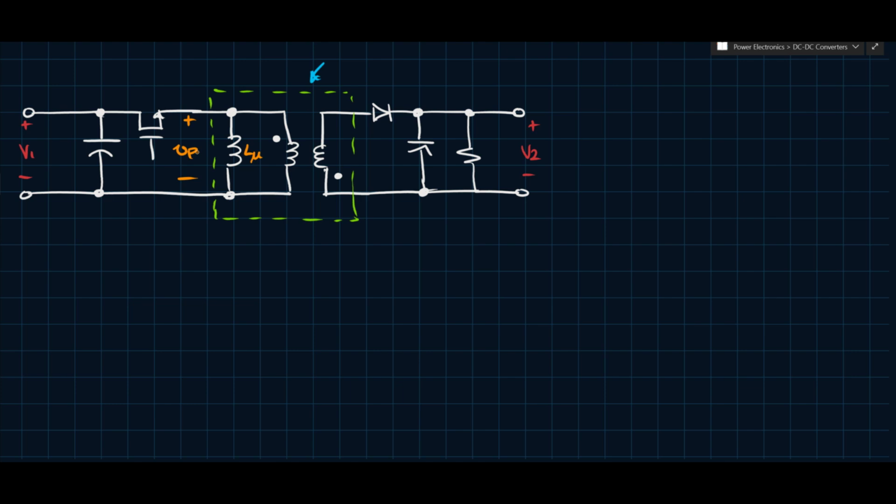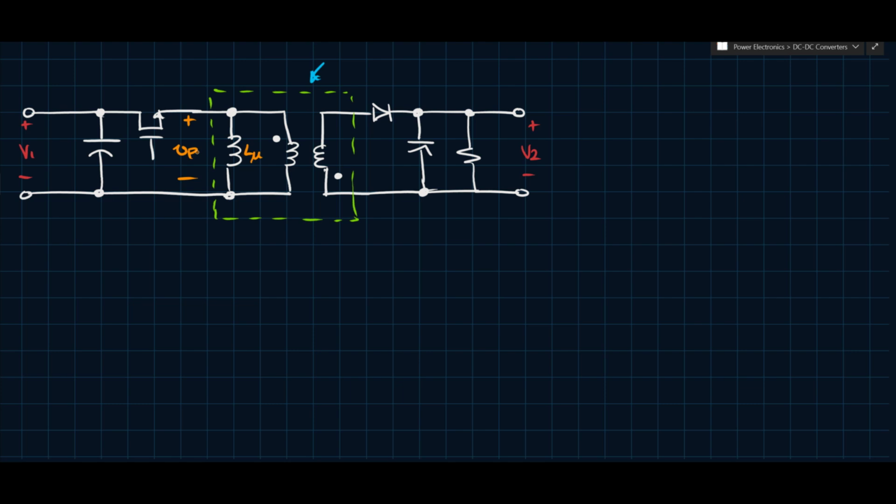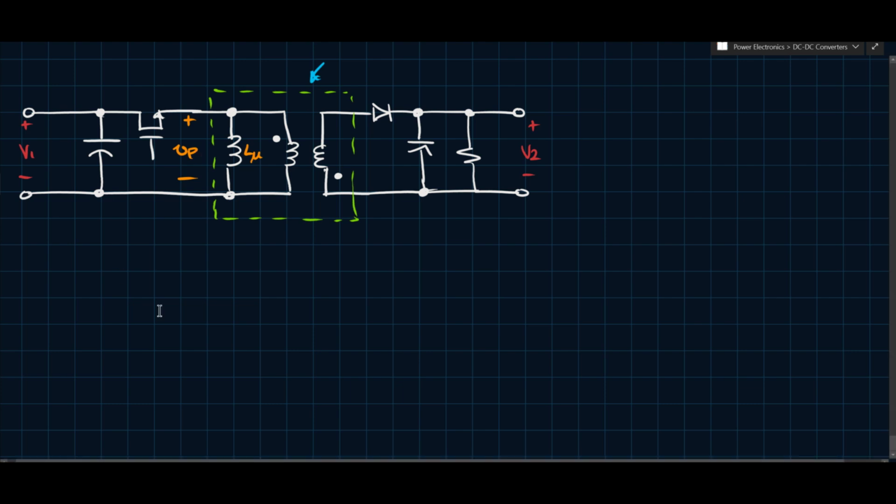There are 2 main types of transformers that are used. Generally speaking, one stores energy and one won't. Some are just for isolation and some are used to store energy. In a case like this, we'll discuss in a second that this one does need to store energy. This is a flyback converter, and the flyback converter usually has what's called a flyback transformer.